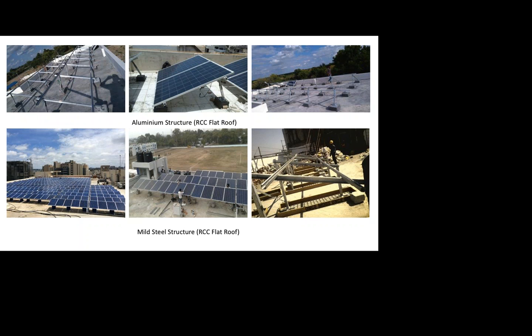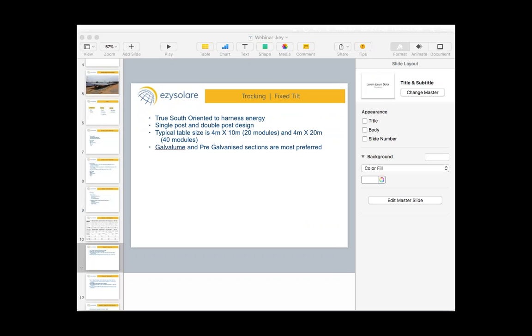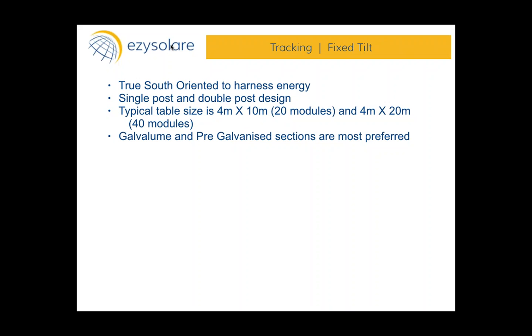So just to summarize, you're saying for anything less than 2 of sheets, we should not be using hot dip galvanized, because it will not be able to handle it. Yeah, essentially not. In hot dip galvanized, we recommend a coating of 80 microns. It's very difficult to achieve 80 at less than 2 without deforming a section.